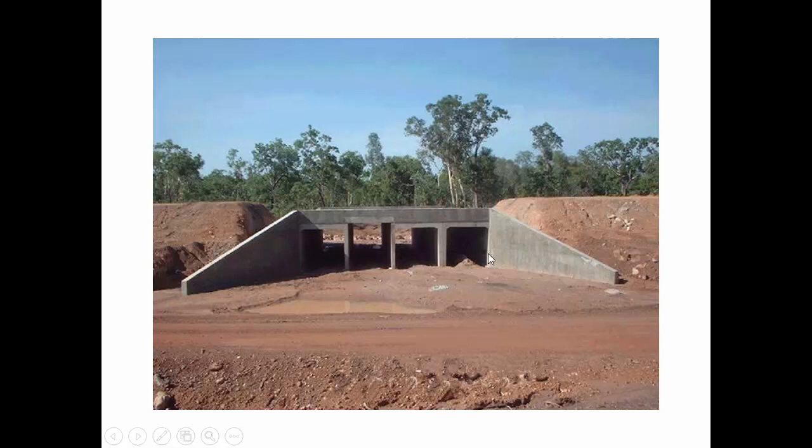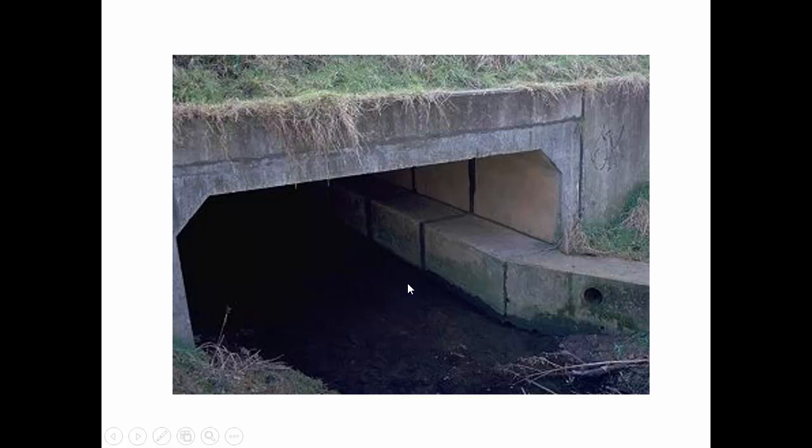But this is also a culvert, and we can analyze its hydraulic capacity in HY8 regardless of whether it's circular or rectangular boxes. Sometimes it's common to allow a natural channel underneath the culvert, so that the culvert is only providing a structure for the road to go over, and if you can, trying to preserve the natural flow of the stream underneath.